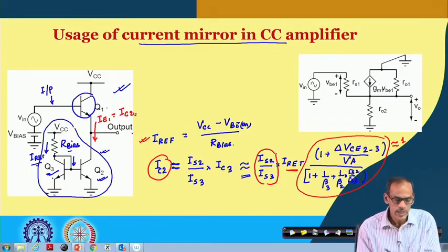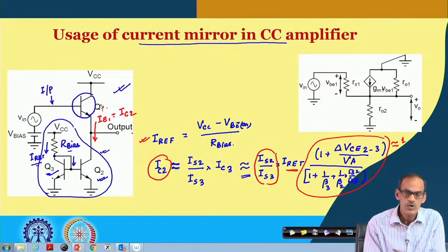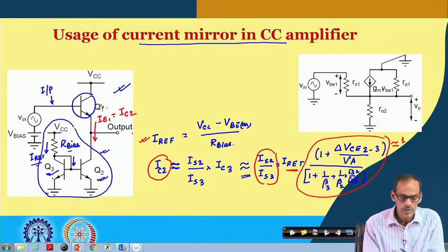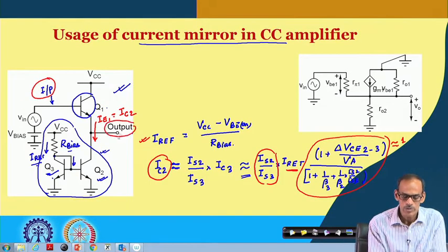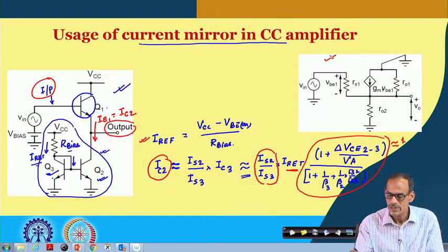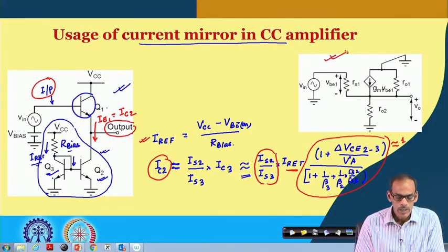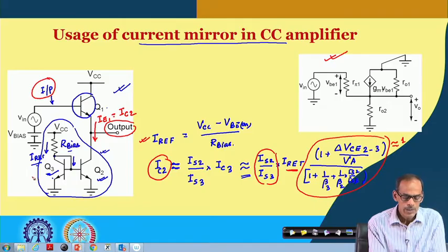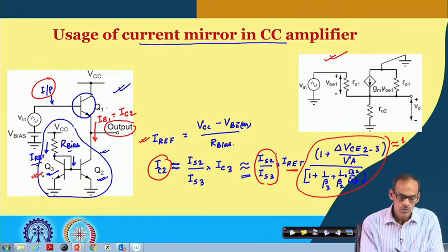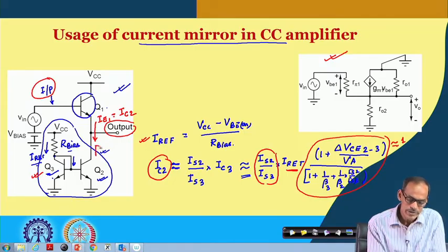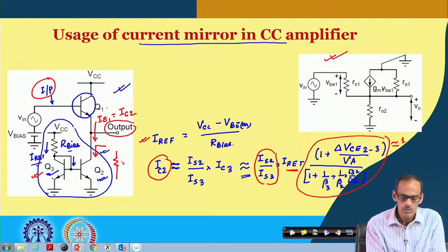Now, once we get the DC operating point, then to find the gain from input to primary output, we can draw the small signal equivalent circuit. Since the current mirror here is not carrying any signal, the small signal equivalent circuit coming out of the current mirror is only RO of transistor 2.